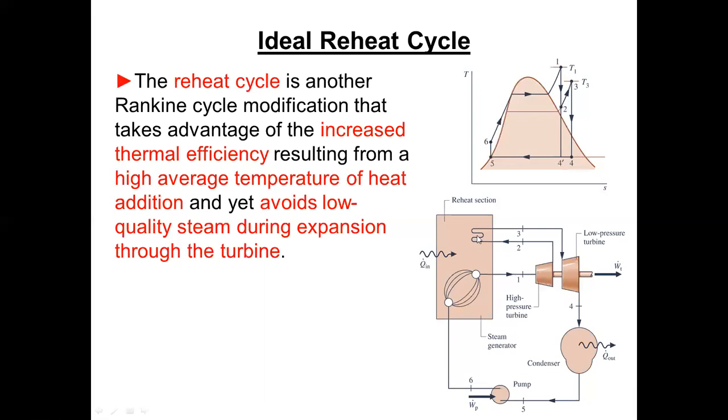We have separate heat exchangers called the reheat reheater sections or reheat heat exchangers or reheat superheater. Probably reheat superheater is what the power industry would call it. So we pick up a bunch of temperature, even though we lose a little bit of pressure, and we go back into the second turbine, which we're calling low pressure turbine. And so this helps us in a couple of different ways.